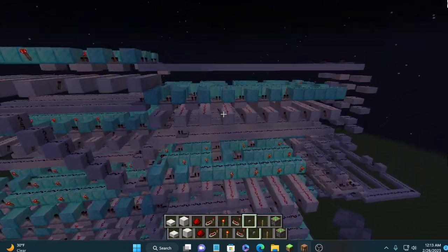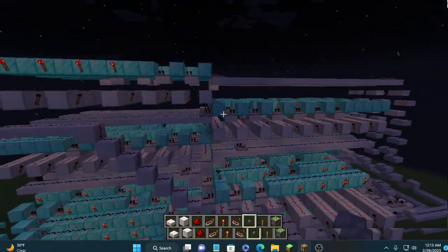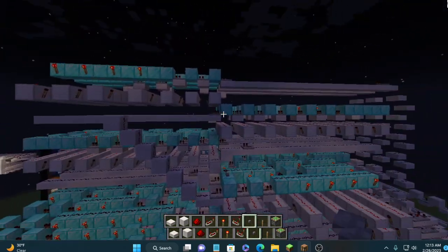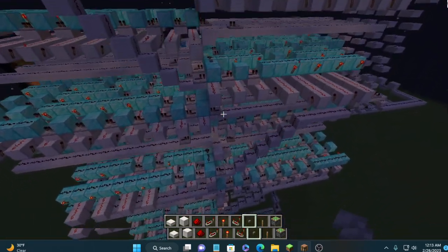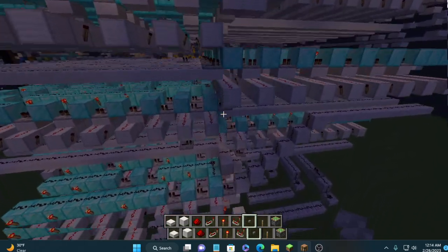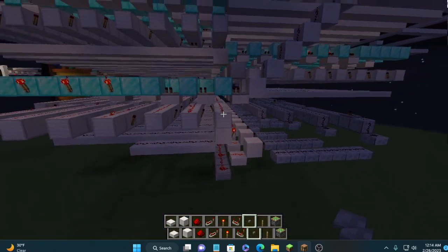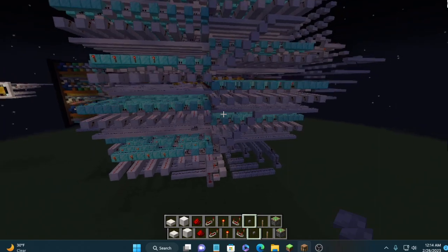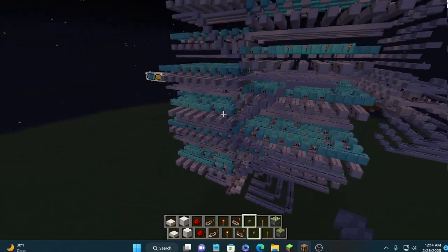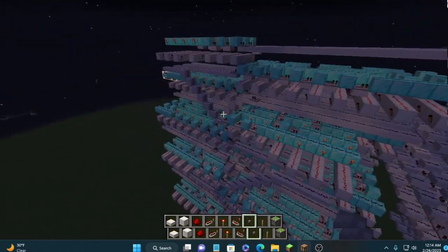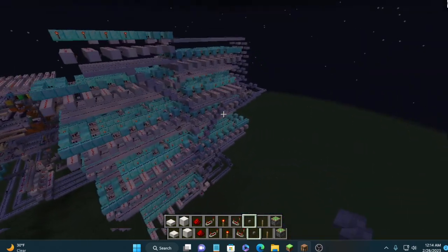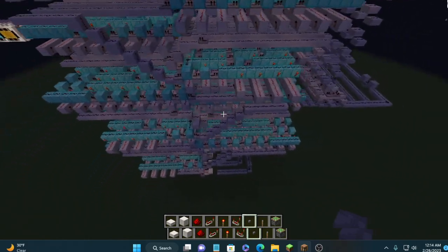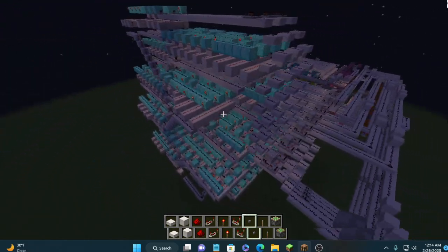This is just a bunch of decoders switching anything larger than a 4, adding 3 to it, and they're staggered, simulating the shift all the way down. I just built it. I knew the algorithm. I built it large enough for 16 bits, and then since I only can go 99 times 99, I trimmed off everything I didn't need, essentially down to 14-bit.